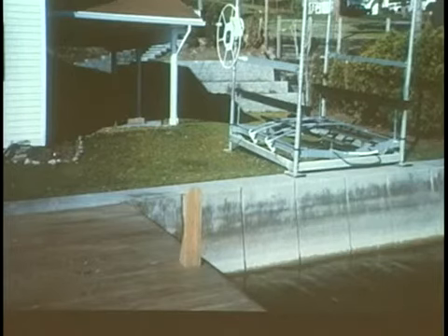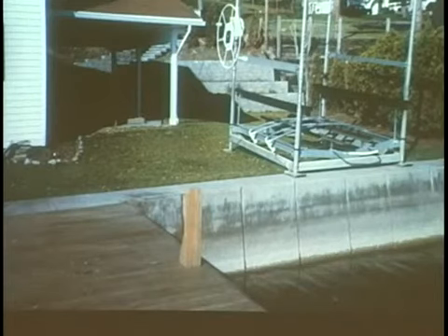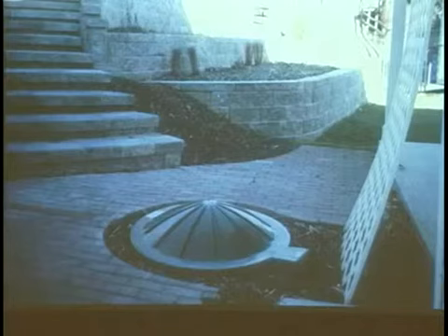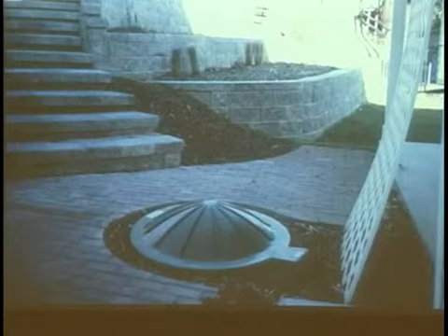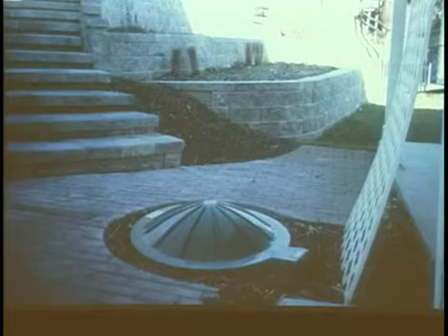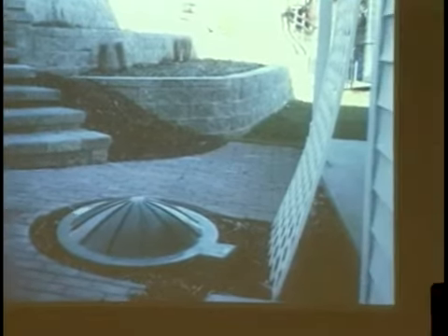We're getting 98% removal of your disease-causing pathogens and bacteria with the aerobic unit. And I've got some vegetation here between that and the lake. I'm going to get some nutrient uptake. And there it is done, totally done. You notice these are at the surface. They need to be at the surface for routine maintenance. The maintenance agreements we have for any of these enhanced treatment units require twice-a-year inspections by the authorized manufacturer's rep. And they copy me on their inspection reports. It comes to my office. This is our control to make sure that these units are operating properly if we're going to put them in.